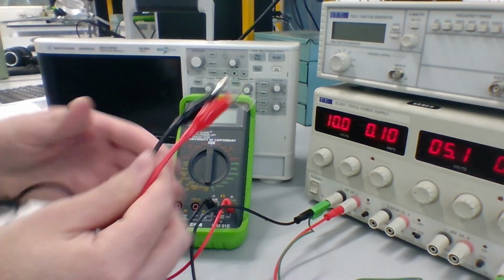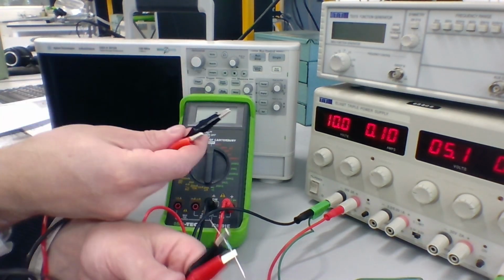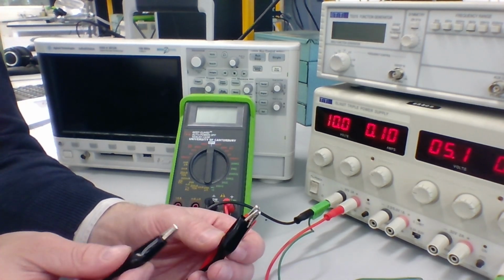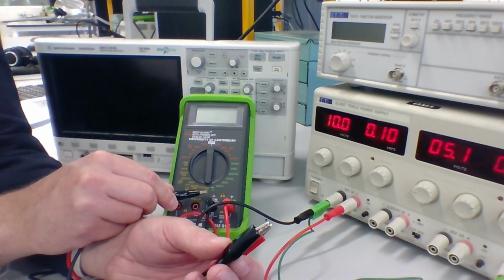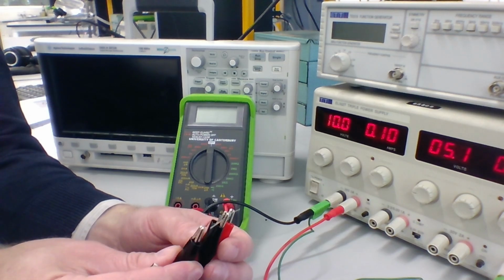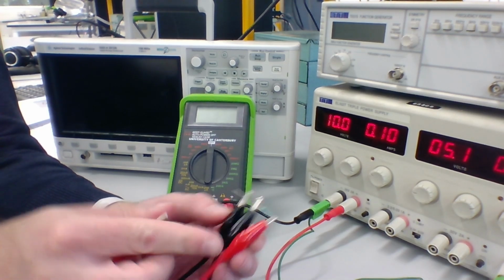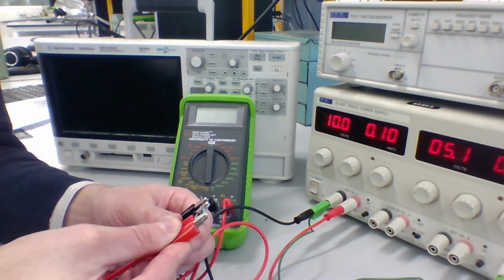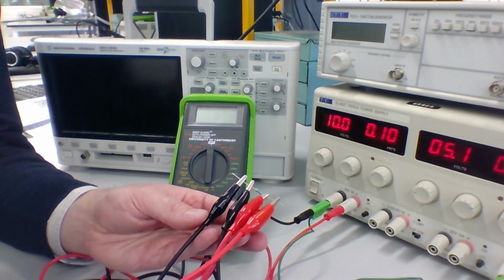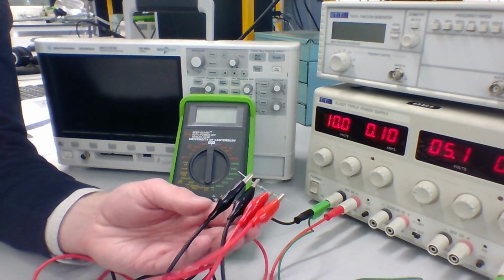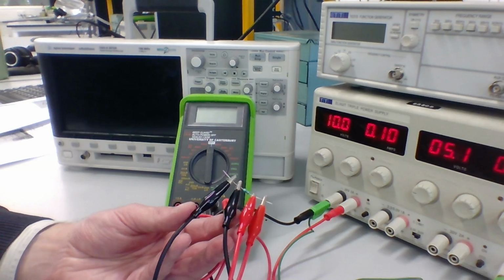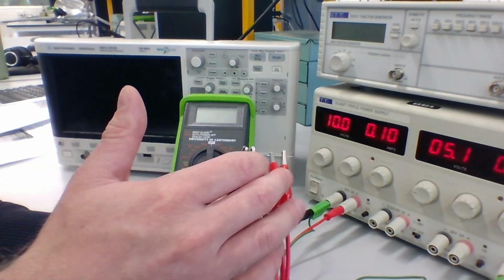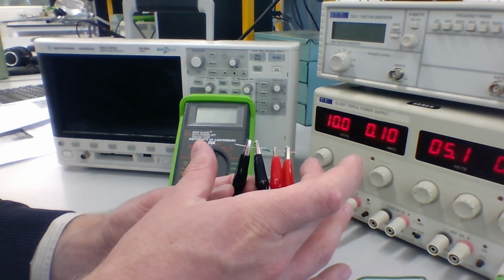Okay, so I'm going to then take the leads from the multimeter and connect them on either side of the resistor as well. And we're going to observe polarity here. So I'm going to connect the ground or negative lead of the multimeter to the ground or negative lead from the power supply, and similarly for the positive leads. Because we're measuring a DC source, it won't matter which way around we do this too much. We'll just get a negative sign instead of our expected positive sign if we connect it backwards. But to make life simpler and easier, it's generally worth following the same polarity unless you have a good reason not to.